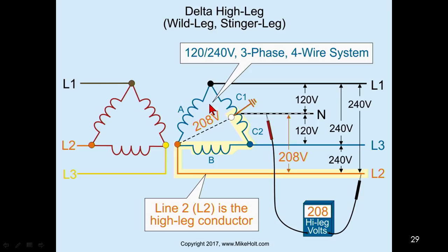Yep. And so a lot of our discussion really has to do with the utility, because you're probably not buying your transformers. The utility will be installing 3 transformers up there, and when you have a Delta system, you'll see 2 small transformers, and all of a sudden a large transformer on the C phase, because they have a lot more line-to-neutral loads than the other single-phase transformers by themselves. Anything else on this part, Eric?